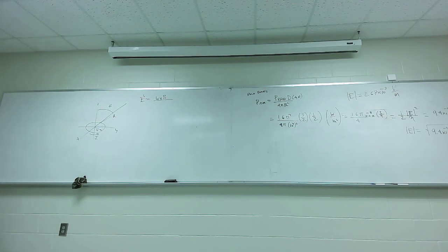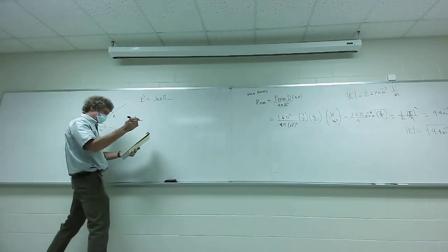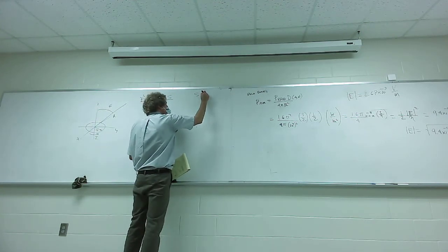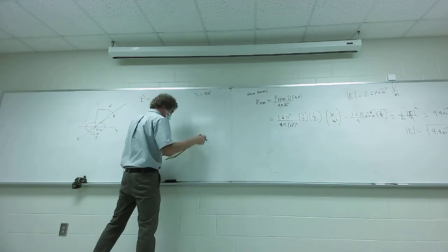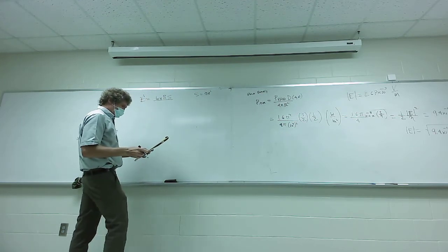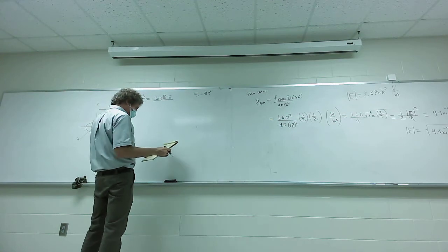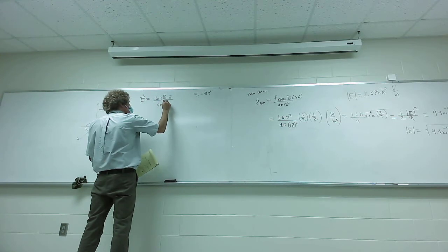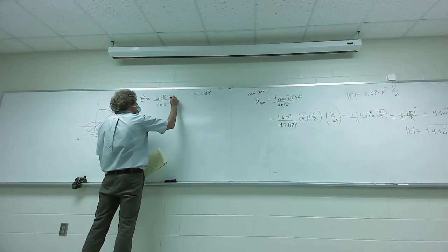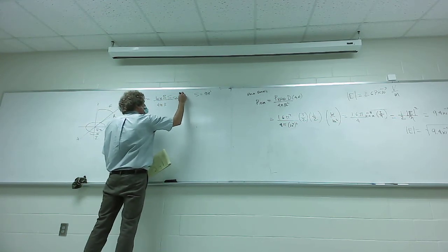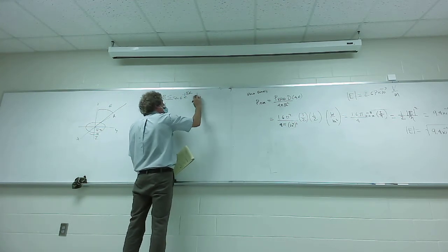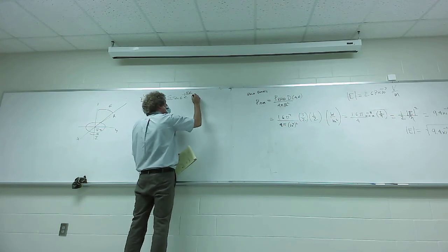So for his loop antenna, it is omega mu beta, and then he puts S, where S is the surface area of the antenna, pi a squared, and he divides that by 4 pi r, pardon, times the sine of theta e to the minus j beta r. However, this is in the phi direction.